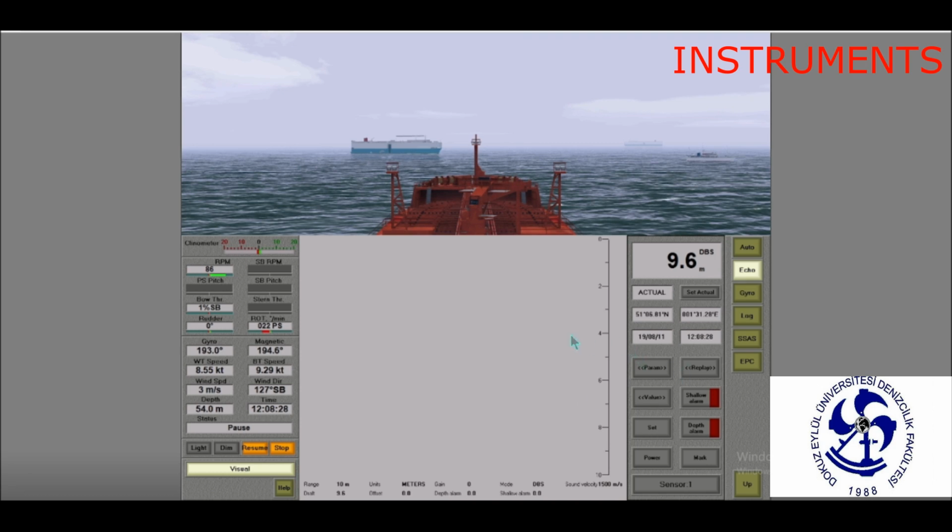There are some indicators and control buttons in the top right-hand side. They are: current depth in chosen measuring units, echo sounder operating mode, actual or replay, current latitude and longitude indicators, current date and time, replay, which allows viewing the sounds of any past moment of time, mark, which draws a vertical line for the current time on the graph, alarm indicators, which inform about dangerous depths and shallows, and switch from one sensor to another.